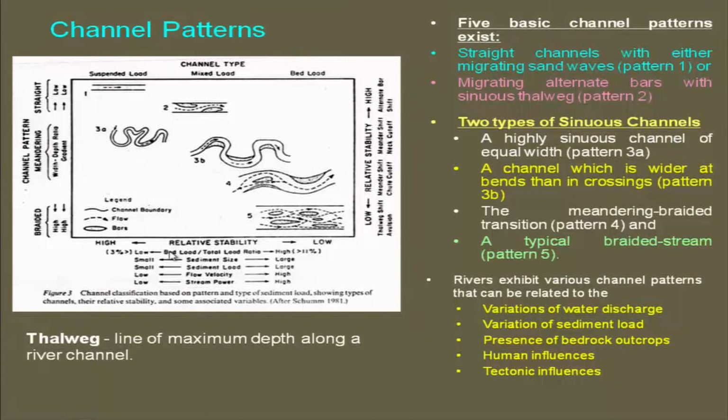This is what has been shown here: the straight channels are highly stable, whereas the braided channels, which have the bed load, have very low stability. So keep in mind that the channel pattern varies from straight to braided, and it is influenced by variation in water discharge, variation in sediment load, presence of bedrock, human influence and tectonic influence.